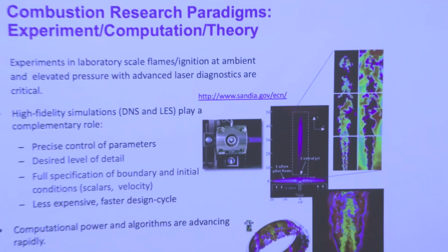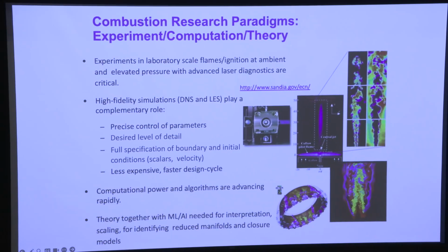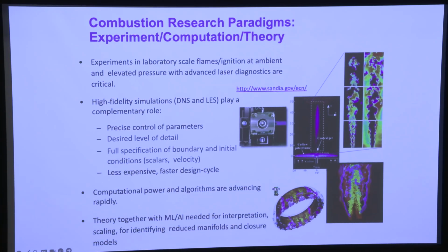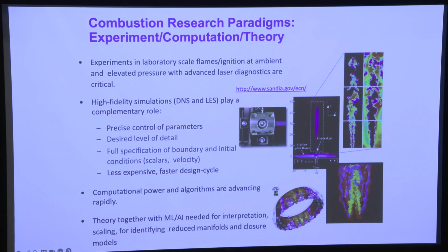Experiments. So the idea here is that we want to combine experiments, computation, and theory. And as I said in the beginning, experiments are in these lab scale flames, and also for looking at ignition problems, have been done at both ambient as well as high pressures using advanced optical laser diagnostics. There's been a lot of development for measurements such as OH, CH, and various other species, atomic hydrogen, atomic oxygen. There's people making measurements of those kinds of species and radicals, and also of soot through laser incandescence.